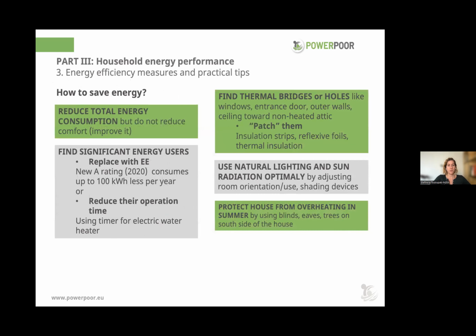So moving on to the energy efficiency measures and practical tips to reduce the total energy consumption. This does not mean that we should reduce the comfort. We should try to improve the comfort: the thermal, visual, and air quality comfort. We should define significant energy users and replace them with energy efficient ones. We should reduce their operation time by using timers, or by using, for example, the heaters during the night if there is a lower tariff during the night.